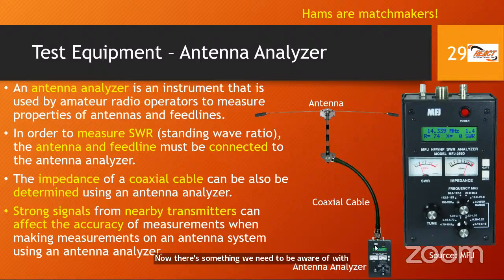Now, there's something we need to be aware of with respect to antenna analyzers. If we have our antenna analyzer, we have an antenna and we're trying to determine what's the resonant frequency, or we have our coaxial cable and we're trying to determine the characteristic impedance of it, and we have a ham radio operator that's operating nearby and transmitting, it can affect the readings of our antenna analyzer.